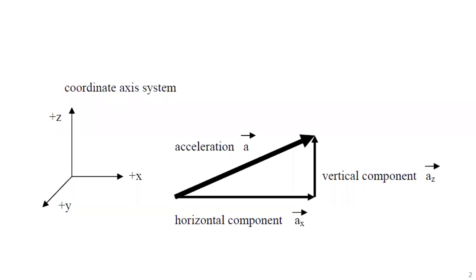So we want to develop the second law of fluid mechanics. The first law we talked about was continuity. We'll do energy, have some fun with that, and then we'll move on to momentum. So as before, we're going to use the same coordinate axis system. Vertical is upwards z, and that dimension is collinear with the acceleration due to gravity. X and Y are horizontal coordinates. They are shown as being orthogonal. It's not an absolute necessity.